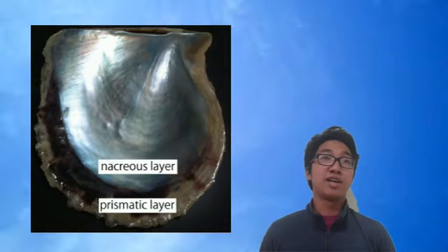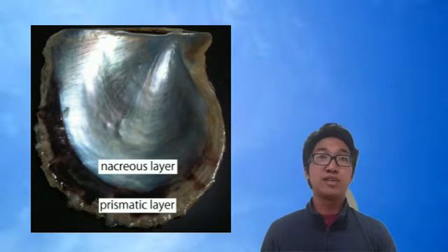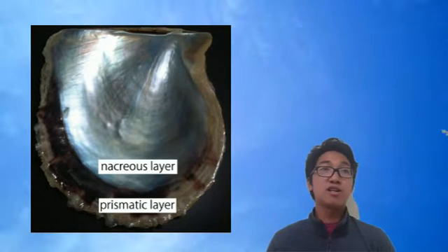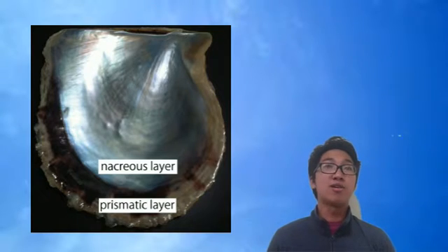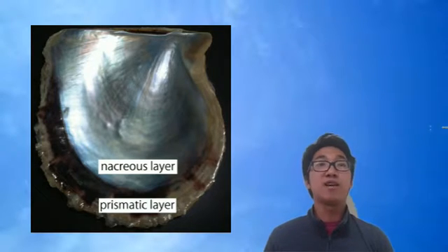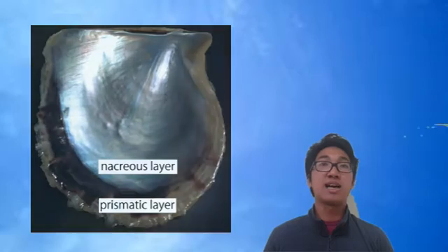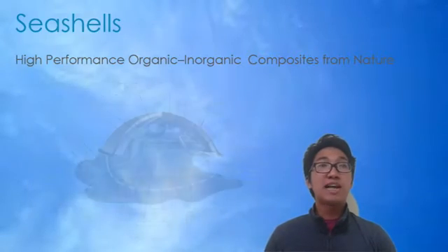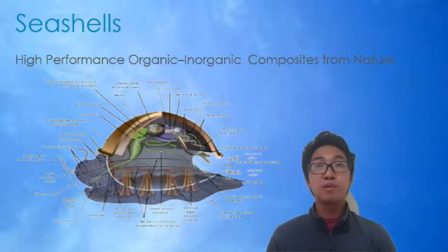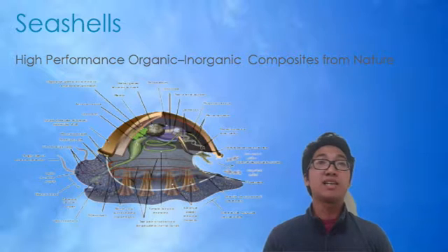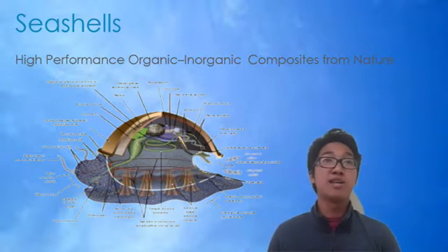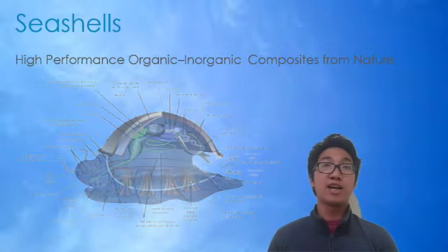The interlining of seashells is called the nacreous layer. It has a 3 order of magnitude increase in mechanical strength. These inorganic bricks are polygonal aragonite tablets separated by a thin layer of soluble and insoluble proteins that act as the mortar. The organic matrix consists of insoluble beta-chitin, serine, and silk-like proteins and does not contribute to the mineralization process directly. Examples of these are collagens that represent the bulk of the organic matrix.